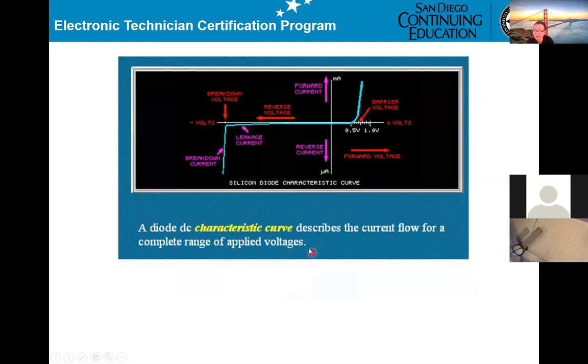Now, that's what they're talking about: the characteristic curve for the diode. I'll just quickly explain to you, not go into too much detail. You see, that is ID, the diode current. Okay, that is the diode voltage. So when the voltage VD goes up to 0.6, 0.7, it does not increase any more. However, the current will keep increasing. You see that the voltage will not increase, but the current will increase.